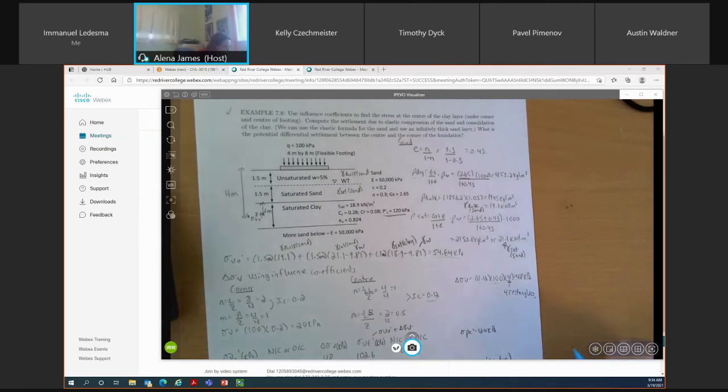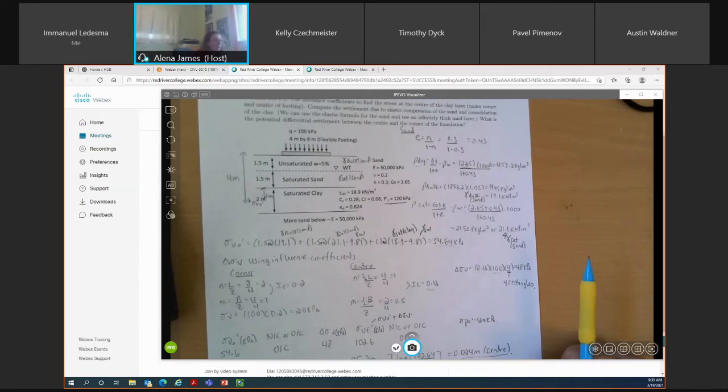So in this question, you weren't provided with your dry density. You have to calculate what your dry density is. But you'll notice in this problem, you also weren't given your void ratio, but you were given your porosity. So you know from your phase relationships that you can calculate your void ratio if you know your porosity. So I went through and calculated my void ratio. And once I determined my void ratio, I was able to calculate my ρ dry value. And once I knew my ρ dry value, I was able to calculate my bulk density. And from my bulk density, I could calculate my bulk unit weight. I'm not going to spend time going through this process because you guys are probably very comfortable with these equations. So I calculated my bulk unit weight of sand to be 19.1 kilonewtons per meter cubed.